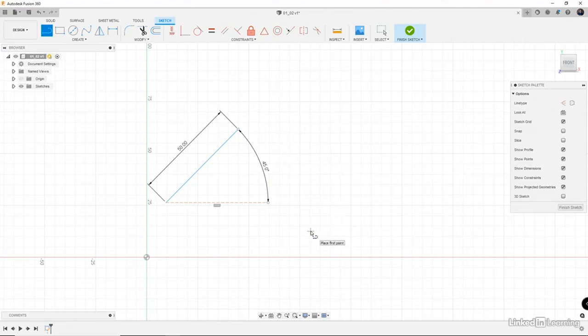We can also come down here and simply create some geometry. Now, by clicking here, it actually launches another line segment directly connected to the endpoint of the previous. So we can come here and just create a really simple pentagon. And you can see that it's kind of snapping to values and giving me constraints on different parts of the line. This line here is parallel, this line is horizontal, and this line is perpendicular. So it's giving me some basic geometry constraints right within sketching.